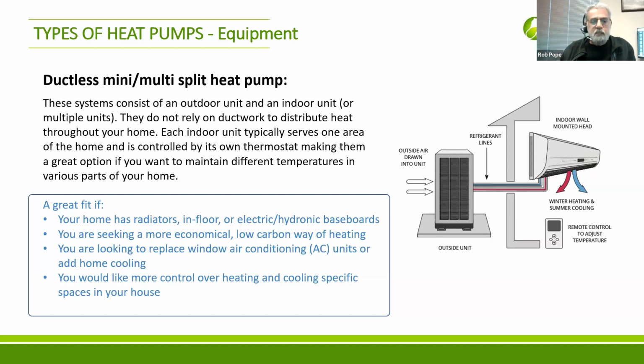The only issue with these, and you've got to be really careful about, it happens in retrofits often. So you've got a radiant system, an old boiler, and you want to get rid of it. You don't want the radiant, you want air, you want cooling, you want to be moving air around. But you can't open up the whole building. It's not in the budget, and you're not prepared to do that. So you put ductless splits, these cassettes on a wall. Problem is that cassette can only heat or cool the room it's in.